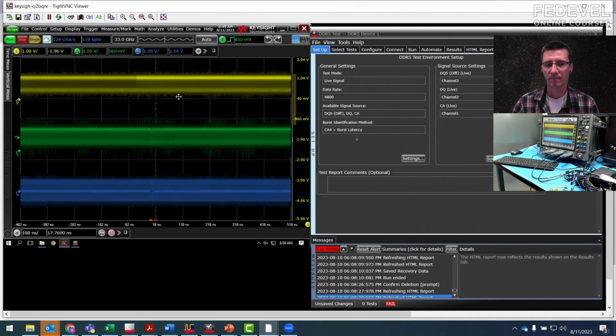So imagine the timing, right? The clock arrives at the first DRAM, and it could be nanoseconds before the last DRAM gets it. We have to account for that flight time. Okay, so that's why, I don't know the exact details, but I know all these timings are set during the training.